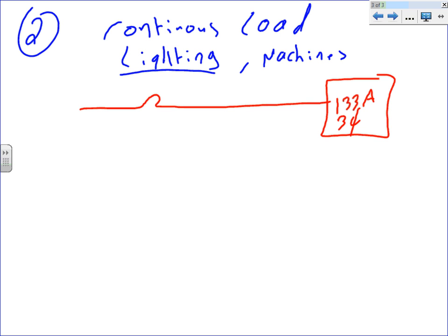I bought this beautiful machine, 3-phase, 133 amps from China, and that machine welds and cuts things and does all this stuff. All I care about is a continuous load, non-motor continuous load. It's highly unlikely to find a non-motor continuous load sometimes. I have the rated amps on it, 133, and they're telling me it's continuous load. We took everything into consideration. Just size for this. Any questions, guys, about this continuous load machine?